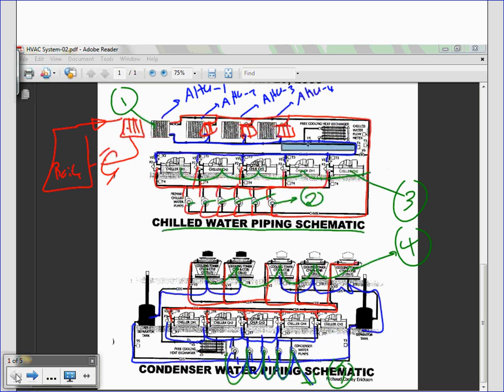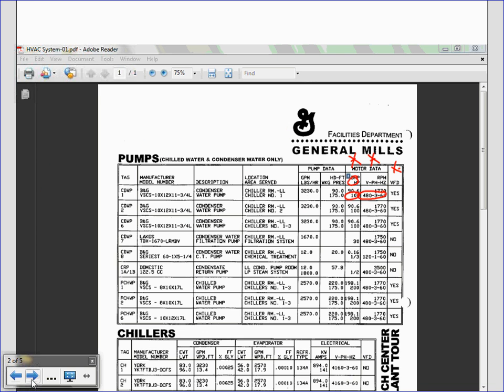You take a building: this chunk of load related to receptacles, we're going to have a panel or panels for it. This chunk of load is for lighting, special type light, so we're going to put it in a lighting panel. Mechanical panel. UPS and data, it's going to be in data panels, like you guys have done the PDUs. Remember the PDUs? What are they? They're just panels specialized for electronic equipment, the servers. Any questions, guys? Any questions, my friends?